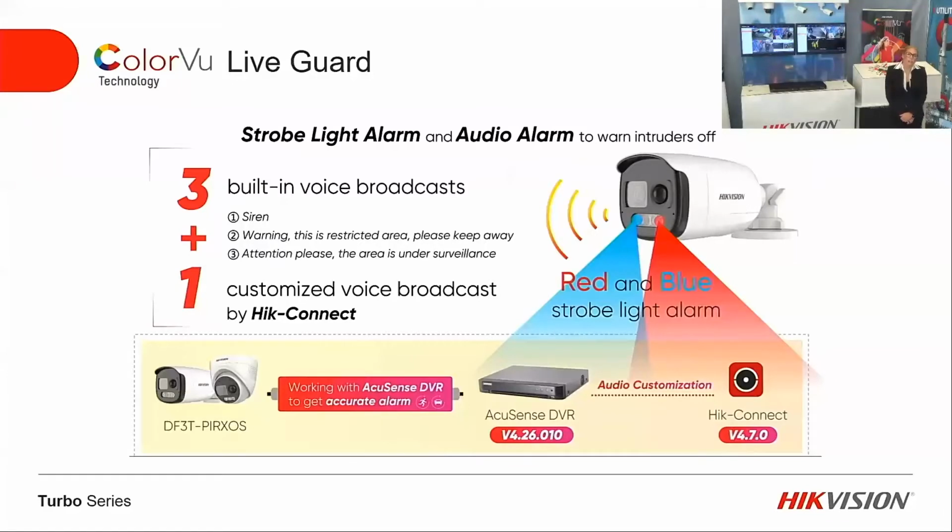The camera image goes into that recorder, and the recorder has a special GPU, like a computer chip built in. And what that does is it analyzes the alarm that's just come in, and it's looking at the image, looking for a human and a vehicle. And depending on how you've set it up, if it detects that, it will push it through as a true alarm. If not, it might be a false alarm. Could be a leaf, could be an animal, could be clouds, lights, anything.